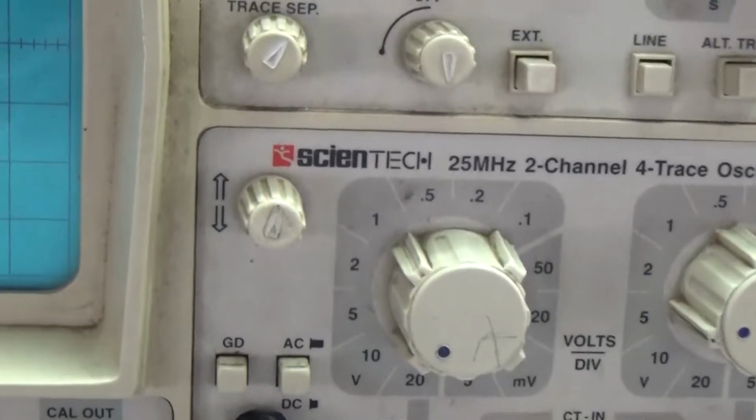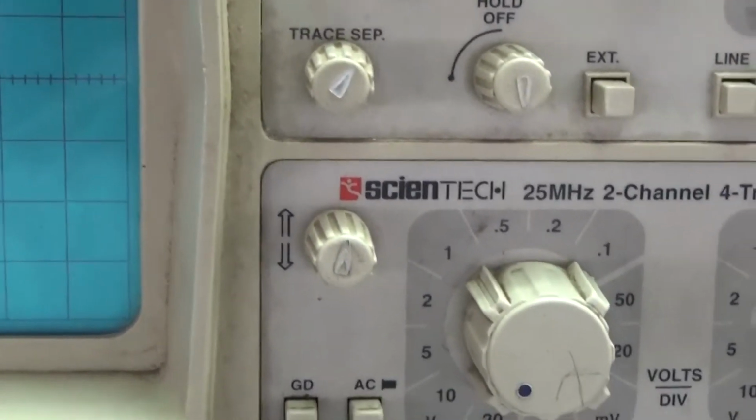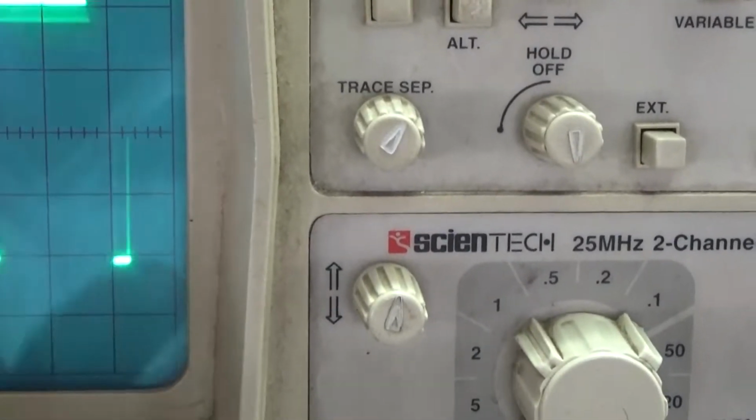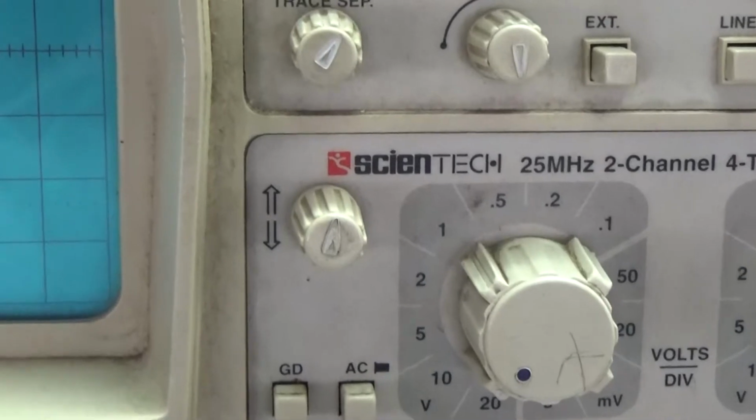Now if you observe, at the moment it is showing the minimum alpha. Now I kept it at one subdivision. So my pulse is starting from one subdivision, nothing but 18 degrees I have set here. Then you go to the second subdivision from the reference. So it is 18 twos are 36 degrees.